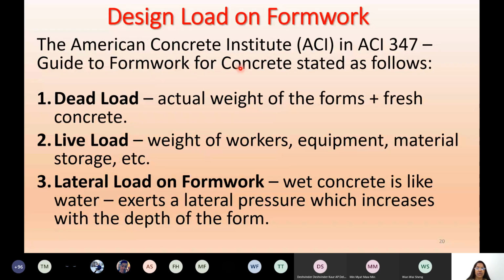Herein I have mentioned the American code, American Concrete Institute, ACI 347, Guide to Formwork for Concrete, which states these are the loads. According to American codes, these are the loads. It depends on the company you're joining, or if you're doing a project, you can choose any one code, either Malaysian code, British code or American code, to follow all through your design. Here it is the American code. Accordingly, in the code book, only 3 types of loading are given for designing your formwork: dead load, live load.